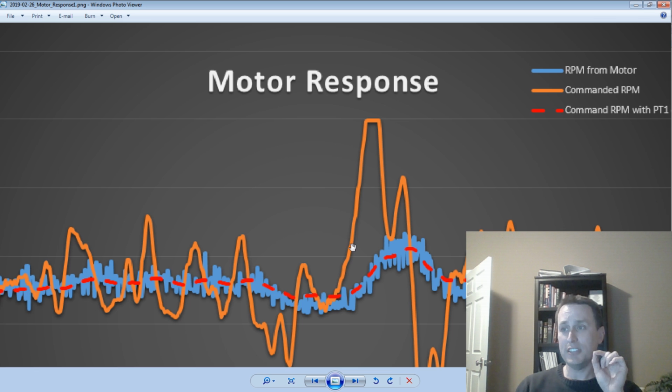Your ESC is commanding this to the motor, so the magnets are powering up to do this, because that happens quick, except the bell can't physically start to rotate faster. Well, fundamentals of energy means that if that energy is not being transferred into motion, where's it getting transferred to? Heat. It's got to go somewhere. So that is the heat being generated.